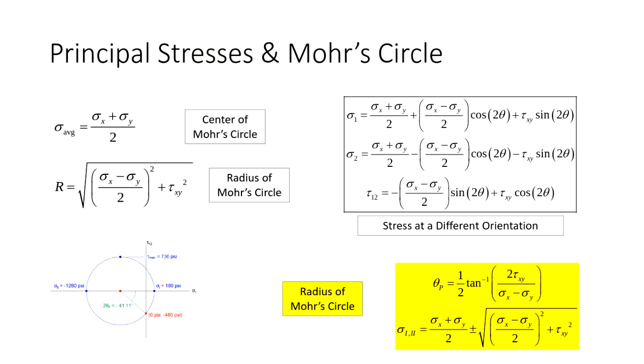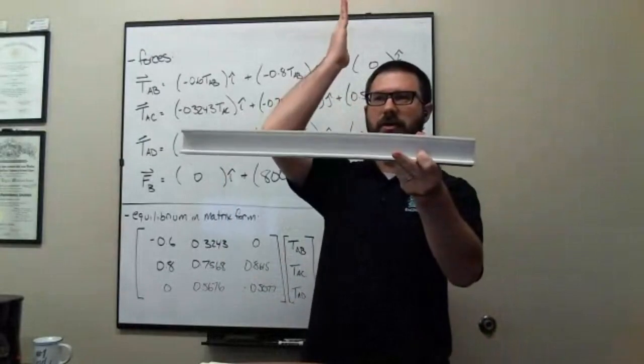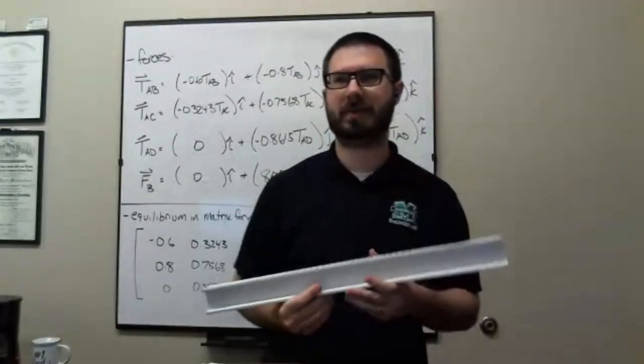Okay. I mentioned in statics and structural analysis and a number of classes I've had that I've always felt that one of the secret weapons of a structural engineer is your samurai sword or your lightsaber if you're a sci-fi fan, because what I'm talking about is cutting a section, right? You have some structure, you have some loads, you cut a section, and then you determine the internal response as a result. Okay. Now, here's the structure. All right. Take the structure, cut a section, and I determine the internal response.